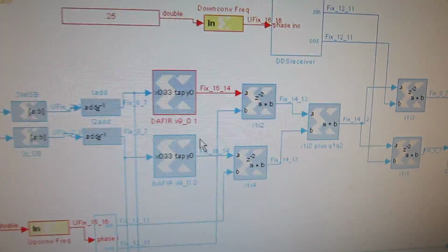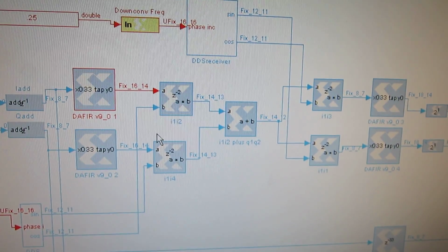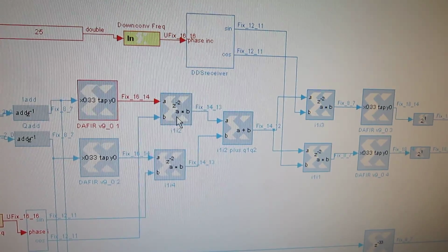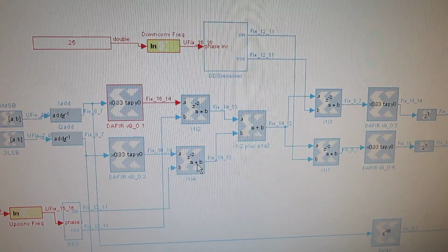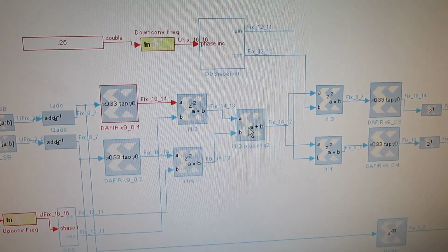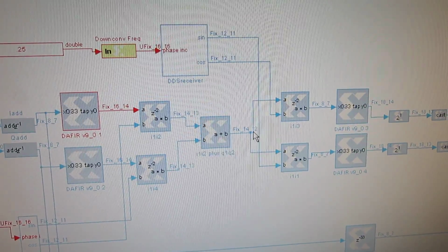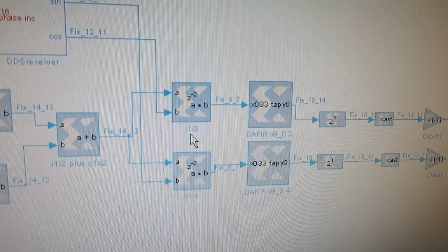We also upsample. Here we modulate the symbols by multiplying by sinusoidal carriers. We multiply the in-phase by a cosine carrier and the quadrature by a sine carrier. We then combine those two for transmission. On the receiver side, we split the received signal into the two channels. We then demodulate it by multiplying again by the sinusoidal carriers.